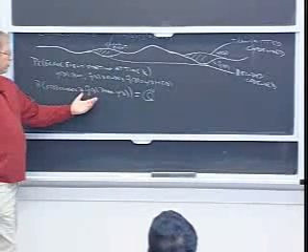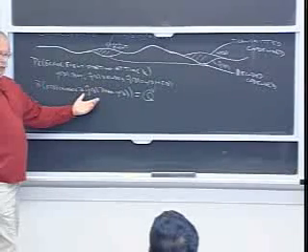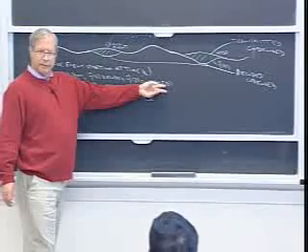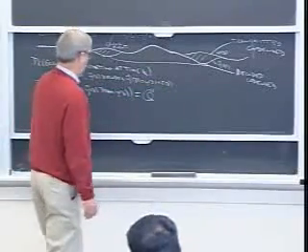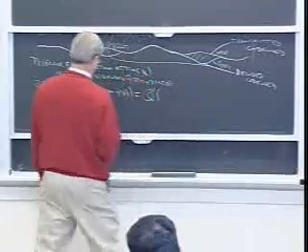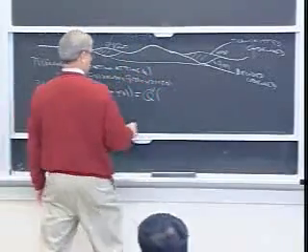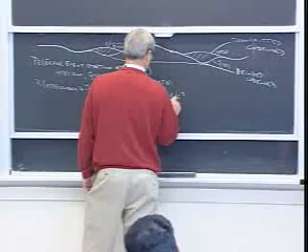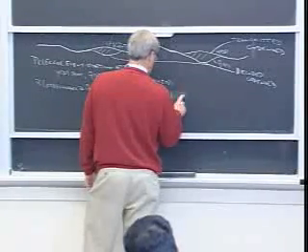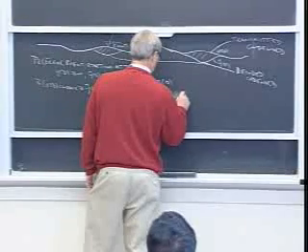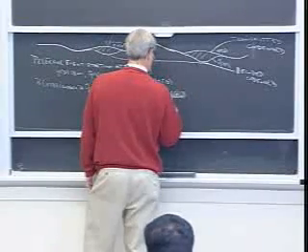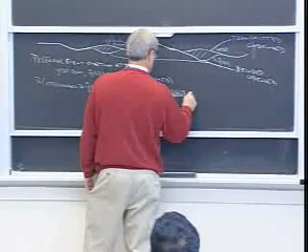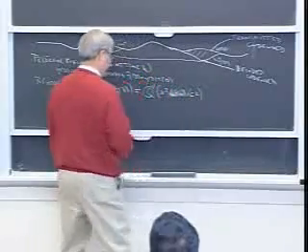What is the Euclidean distance between them? It's 4 alpha squared times the Hamming weight of this error event. And if you remember how to calculate pairwise error probabilities, this is just Q of the square root of alpha squared d over sigma squared, where d is the Hamming weight of e of D over sigma squared. Do you remember something that looked like that?